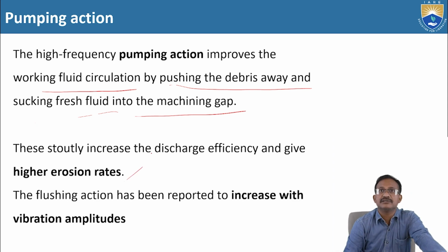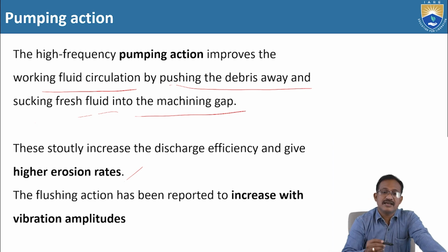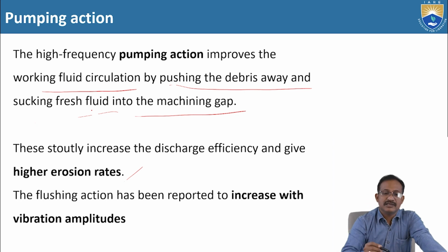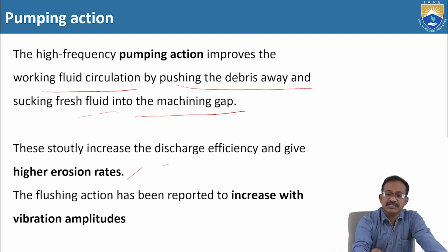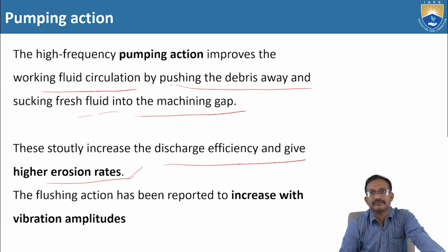Why? Because the debris will flush away and it constantly sucks fresh fluid into the machining gap. So that's why it increases the discharge efficiency and gives higher erosion rates.